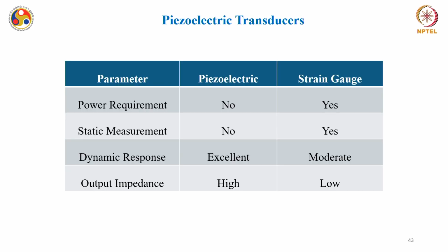If you compare it with the strain gauge, of course piezoelectric transducers do compete with the strain gauges. There is no power requirement, so basically they are self-powered devices, okay. Dynamic response is also much better as compared to the strain gauge based devices, and output impedance is also good enough, okay. So if I have to compare a piezoelectric transducer against standard devices like a strain gauge, I can say that these devices perform much better.